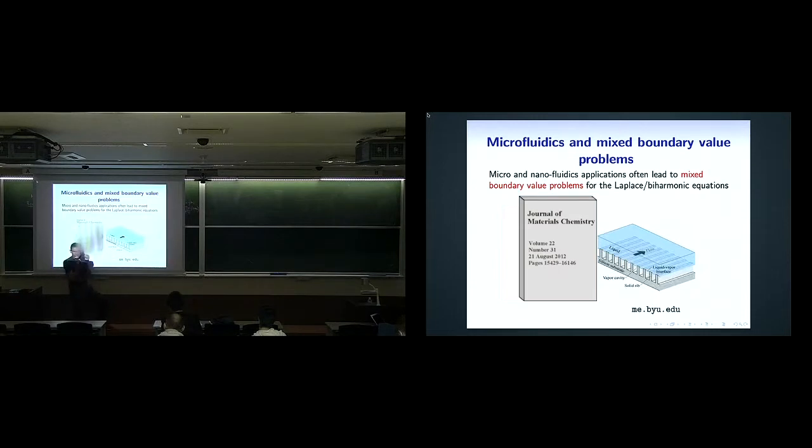And what happens is, because these are so small, surface tension is active here to allow a little meniscus to form between the pillars. Now, that's very good, because it allows the fluid to slip. So when you're pushing fluid this way, it slips over these, which means that the pressure gradients needed to push the fluid through are much smaller. But they don't transfer heat to the fluid as well, because it's now air. This is full of air. And here's the hot microchip down here. So the heat has to be transferred through air to the free surface now to get to the liquid.